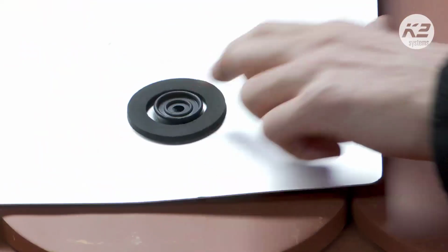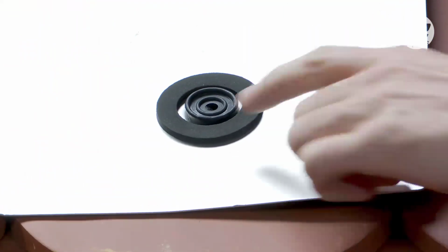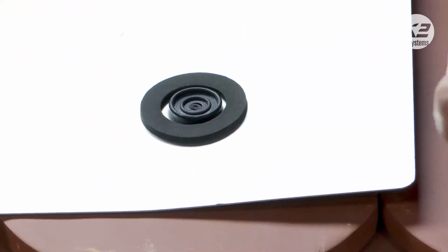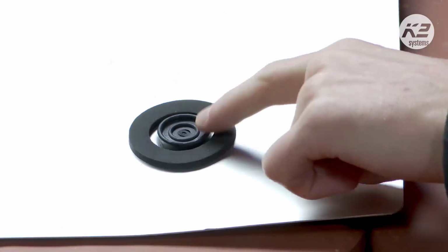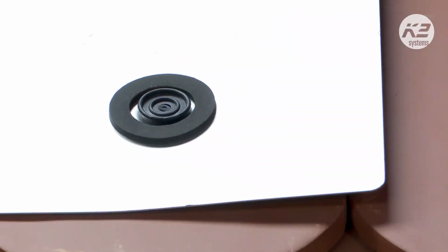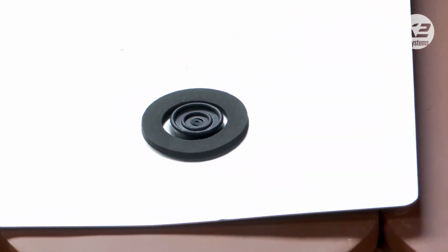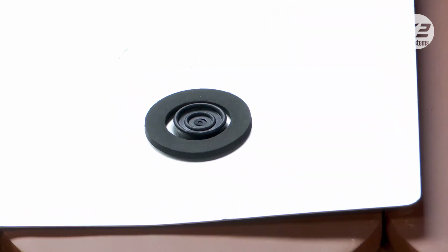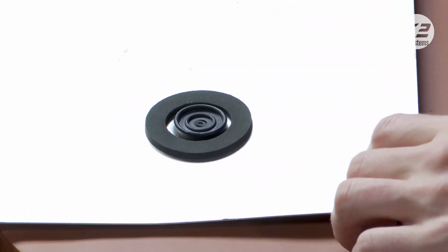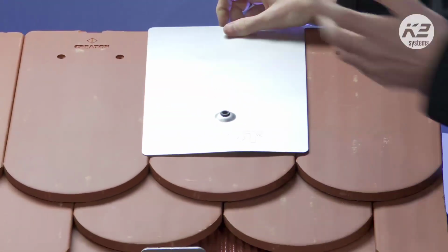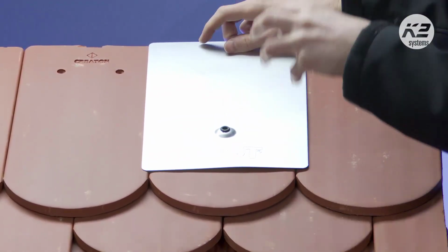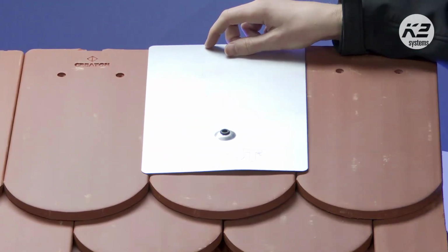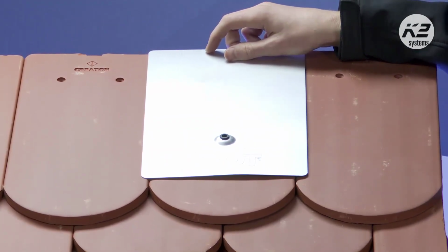And then we have even more, a bit of a plug, I would say. This is a rubber material which, as it's compressed, because we're going to turn over and screw in, will provide another sealing level around the tile, and therefore into the batten, reducing any chance of water penetration. This will just sit on top, screw through the tile. There's very little impact force provided onto the tile itself.